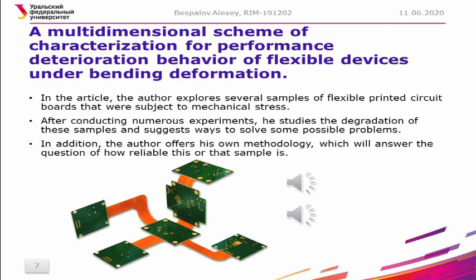The third task in this project is related to the requirements for placing the control system inside very small spaces. For placement in a small volume, it is necessary that not only the devices be miniature, but also the cables that connect them. In order to save space, the technology of flexible printed circuit boards will be used in the project. This will do without cables and connectors between the control system devices. It will also allow us to do without soldering wires, which is not very technological and does not withstand high mechanical loads.